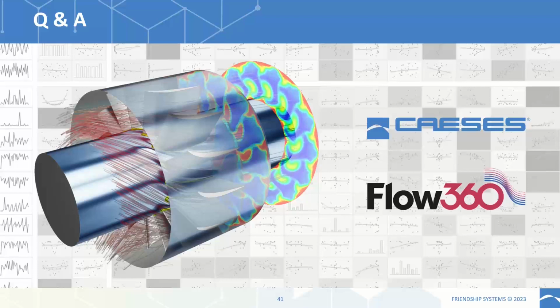And maybe, Payam, there is a little bit that you can say about the automation on your side. Basically, if the question is how the mesh is being generated, the mesh is automated through solid meshing. We automatically generate the mesh over a solid, and the solid is watertight. We get a watertight BREP from Cases, and then we generate the mesh. To customize the mesh, we use surface naming, and based on the surface naming, we can tune the surface mesh over a particular region, for example, leading edge to leading edge. And then after the mesh is completed, the mesh is uploaded.